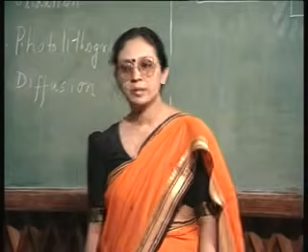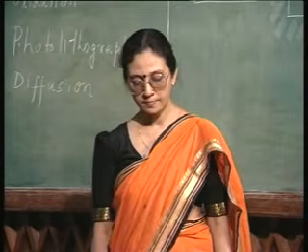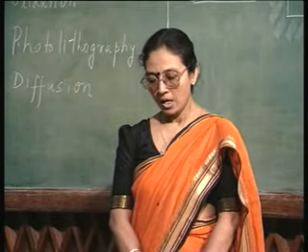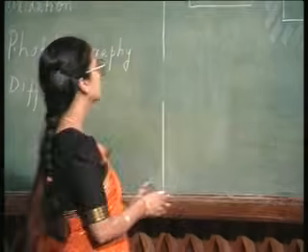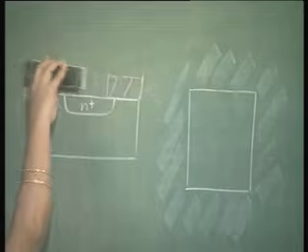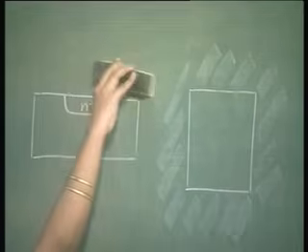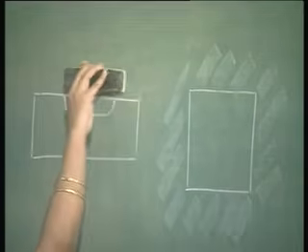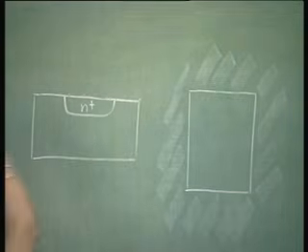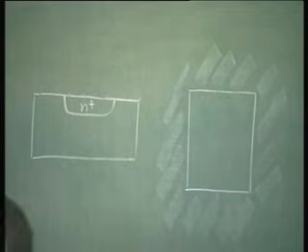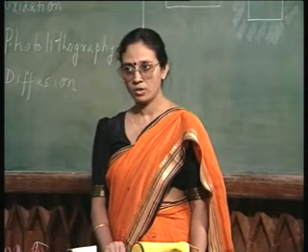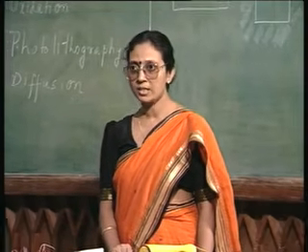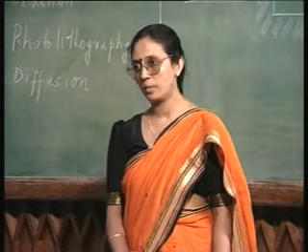After the buried layer diffusion, we remove the rest of the oxide. So, the structure is like this. You have again the bare silicon substrate, in the active region it is doped N plus.